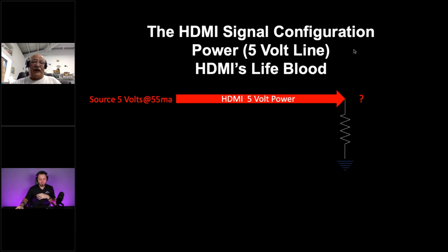So once you put a load on it, it gets to be a little bit testy. But now I'm going to tell you some real interesting things. So here's our current draw, right? And you see, now we go less than 5 volts. Now we're at some number less because we're drawing current now, right? Well, the TV on its own, when it's turned on, draws 10 milliamps. So you don't have any but 45 left. We're already sucking 10 out of it. That's now almost 20%, you think about it. Your AOC, you just lost another 10 mils.